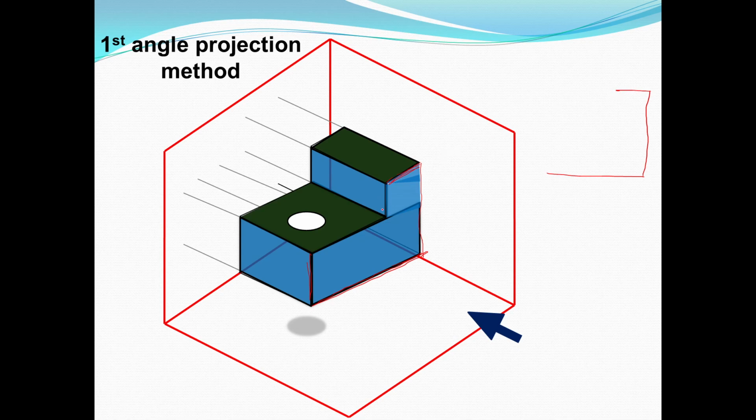So now you can see the vertical surface or vertical edge. Whatever dimension you know from the drawing, make the vertical line here, and again a horizontal line. It's something like this. In the front view you can see this part, there is some hole, and the edges of the hole are not visible, so you have to draw the hidden lines for the hole.